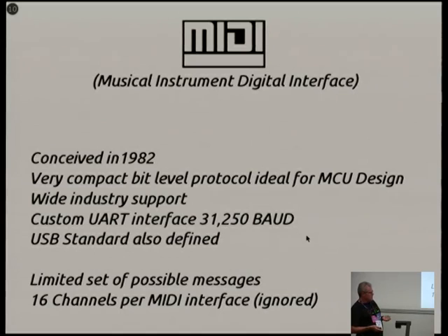The actual size of the data itself is generally 7-bit. So if you're moving a fader, you're only going to get a 7-bit signal, which is from 0 to 127 as a value range, which is fairly grainy. Particularly if you're moving it fast, you tend to get that zipper kind of effect. The human ear can notice it. Each channel allows you to have one 14-bit signal, which is your pitch control. But again, you've only got one per channel, so you end up really trying to hack to get more than one of those in. If you're building a multi-fader device, you very quickly run out of options, short of making it look like a multi-USB device.